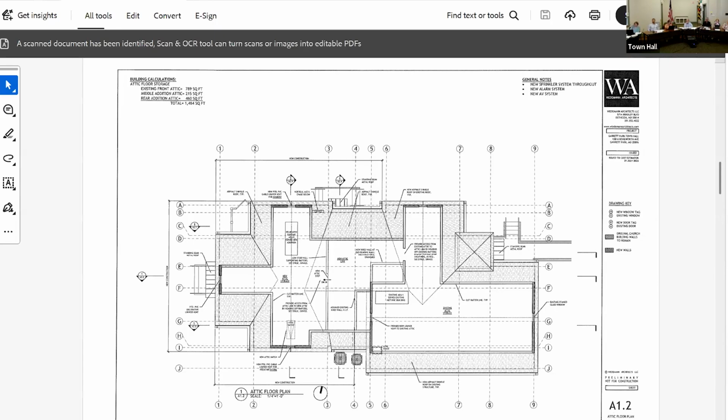The other thing is that the roof on this building is currently a little more than 15 years old, between 15 and 20 years old, and it's a 25-year roof. So one thing we've done is we're putting in a new roof. They don't use the term 40 and 50 year anymore, they use lifetime asphalt roofs now. But we're going to be using the higher quality asphalt fiberglass roof for the existing and the new.